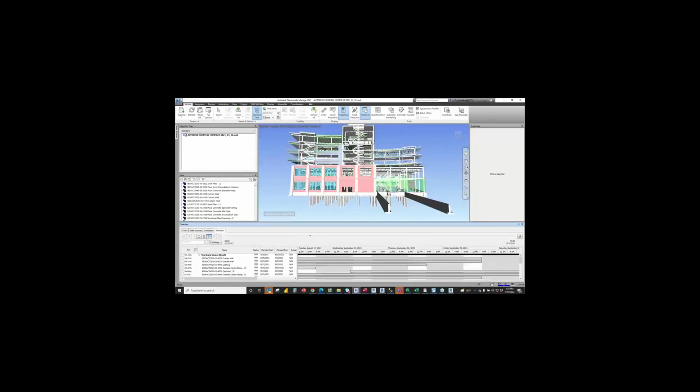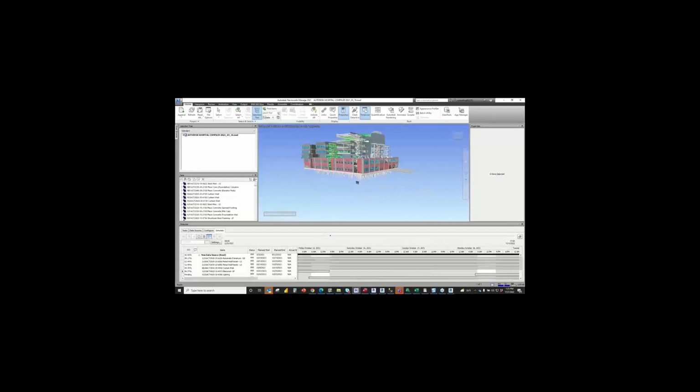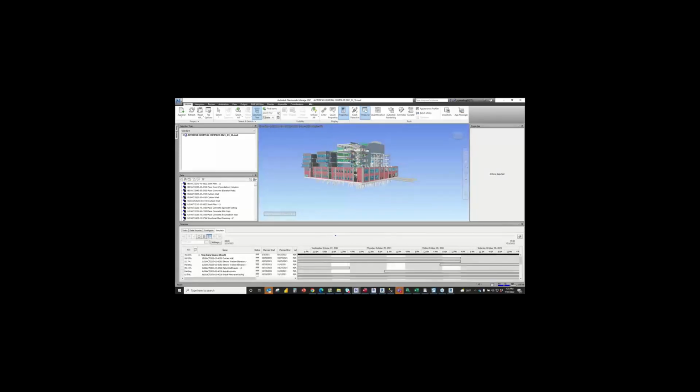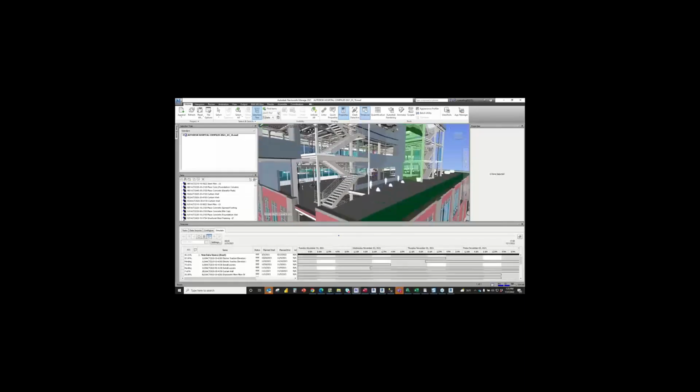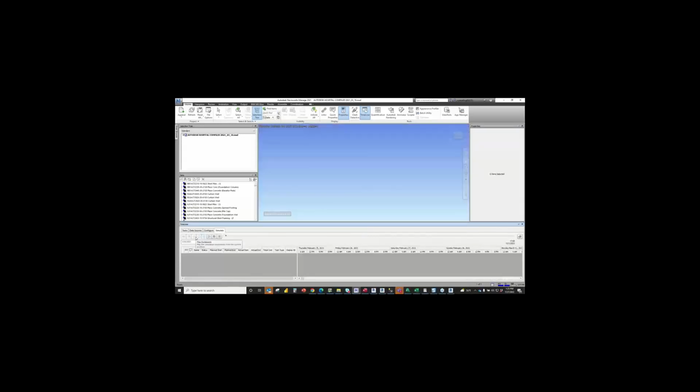And I mean, if anyone here on the call has ever had to do this via Navisworks or set one of these timelines up manually, the selection set portion is extremely time consuming, especially when you're getting a Revit model pushed into Navis and how it's creating your hierarchy within your selection tree. What Rich has done here in using Assemble to create and condition that model to push that to the XML in order to create the selection sets, but have it perfectly mirrored over to the schedule tasks.